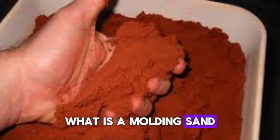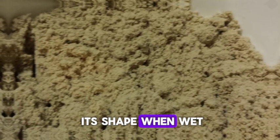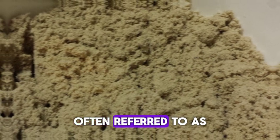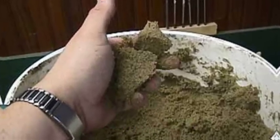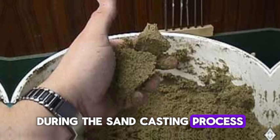What is a molding sand? Sand that tends to pack effectively and maintain its shape when wet, compressed, greased, or heated is called molding sand, often referred to as foundry sand. It is employed to prepare the mold cavity during the sand casting process.